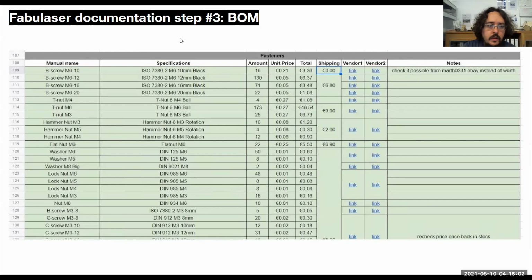All right. So the bill of material, guys, is the holy grail, the source of information for many aspects of machine production. Of course, it's used to order the parts, it's used to group shipping, and I use it also for production because I divide my bill of material into different sections. For example, I have CNC mill parts, all the fasteners, laser cut parts, 3D printed parts, and so on. But it's also used for documentation, because the naming is something that you would use to communicate to people what the components are.